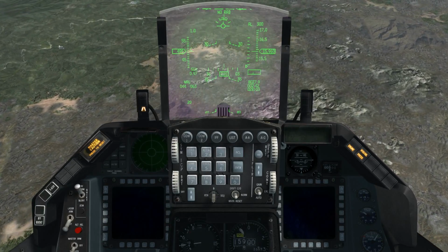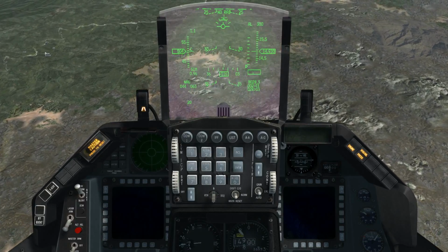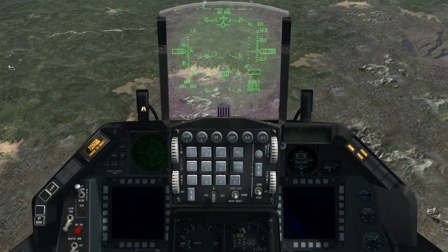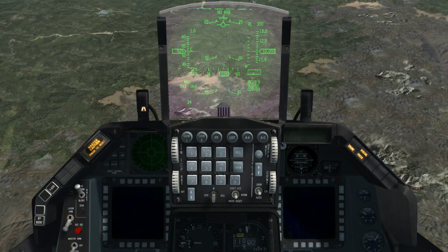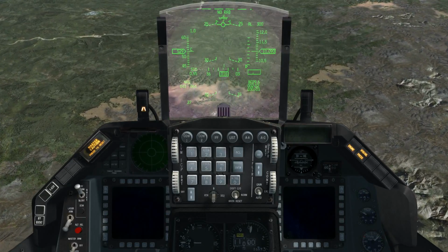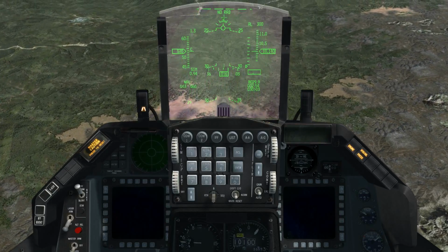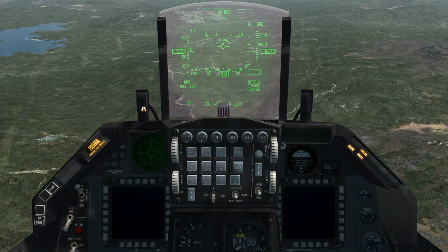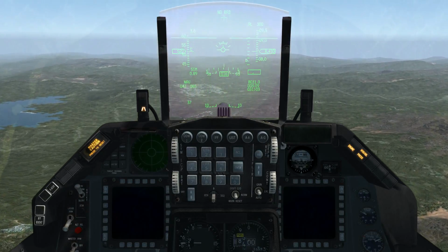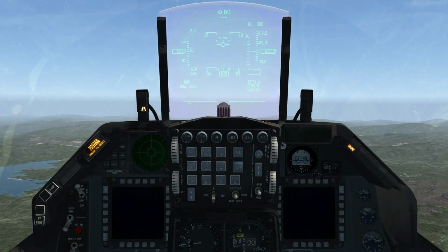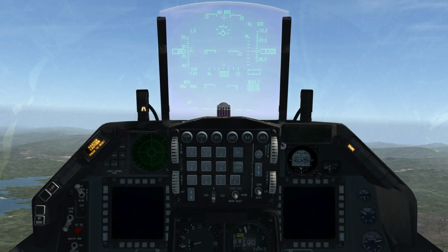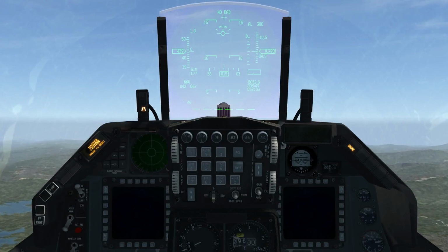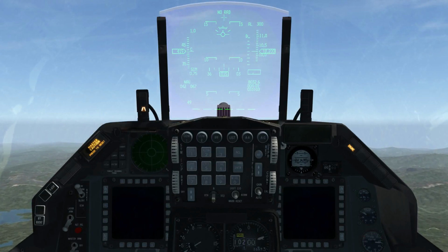Coming up on 22, mid-range on the throttle, idle detent, throttle to idle, and there's the restart. Now I want to trade this altitude. Anything in excess of 250 knots, I want to trade airspeed for altitude. So we got down to 8,000 feet or so. So I want to zoom back up here and get some altitude below me in case I have to do another restart for some reason.